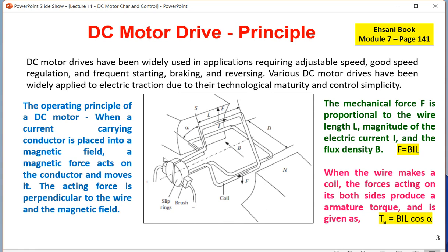So a part of the armature current goes to the field, and that is called the field current, and that is producing this electromagnet. Now between north pole and south pole, from north to south, that is the direction of MMF. So this B actually is shown like that. B is the direction of MMF, that is the magnetomotive force or flux lines, and B is actually called the flux density. So the more current you give to this armature, the higher the torque generated, and accordingly.